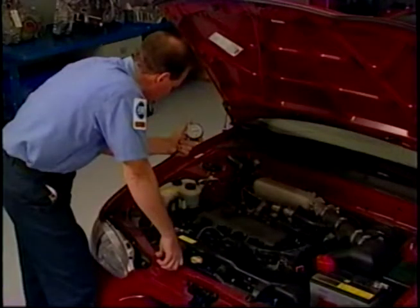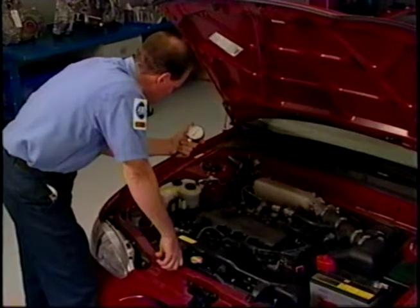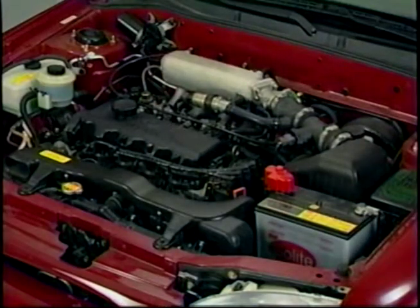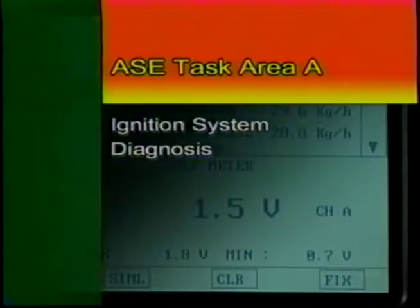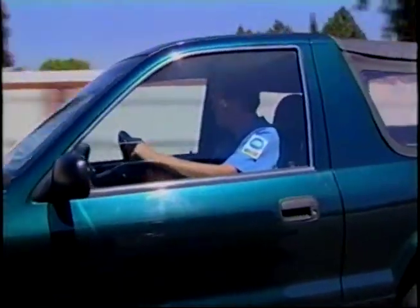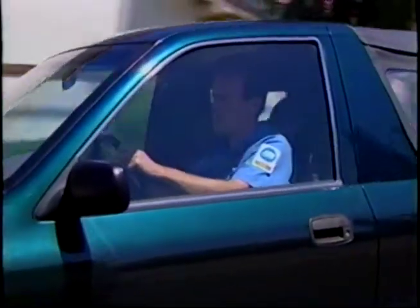If you're dealing with a concern of a rough or uneven idle or low power, pull the spark plugs and do an engine compression and cylinder leak down test to confirm that the engine internals and valve train are not the cause. If the basics are all within spec, then move on to confirming the operation of the ignition, fuel, and emissions control systems. A road test of the problem will probably give you a clue as to whether you're dealing with an ignition or fuel problem, so where you start is dependent on the complaint.